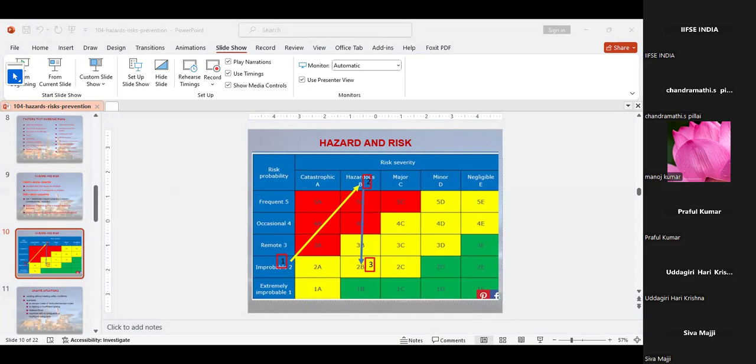Yes, sir. See, this I have done for an oil company called Taka Energy. As I have shown in the PowerPoint, I have used the risk matrix here. Apart from that, you need to write what activity you are doing. This is work at height above 1.8 meters. In the Middle East and other countries, we take 1.8, but in India it is 2 meters. Then the date of assessment and your document reference.